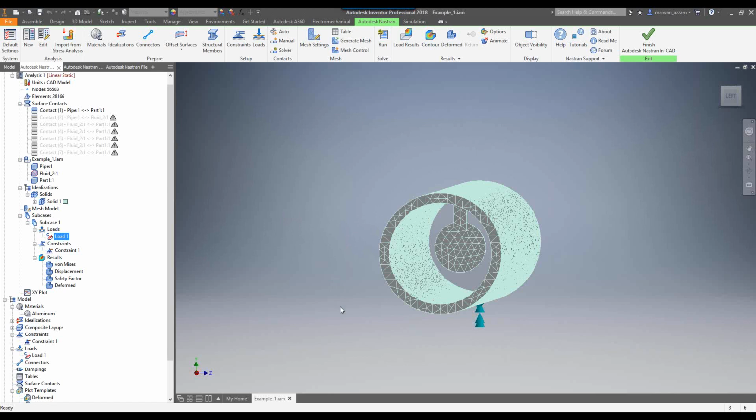They have to be the same size and the same orientation. The mesh size doesn't matter because it does a spatial mapping and will interpolate, so you don't have to use the same mesh size between the FEA and the fluid model, which is great. But they need to be the same size and orientation. Otherwise, I'm not sure what you're going to get.